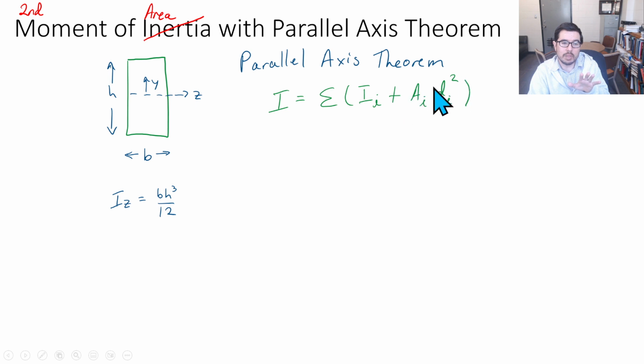You could sometimes, if you were to increase the width of the beam, for example, of this cross section, that's kind of like saying I have one I, another I, and I can put them together. They have the same neutral axis. The centroid of that object is in line with the neutral axis that we already have. The centroids are aligned, so we don't have to use any distance.